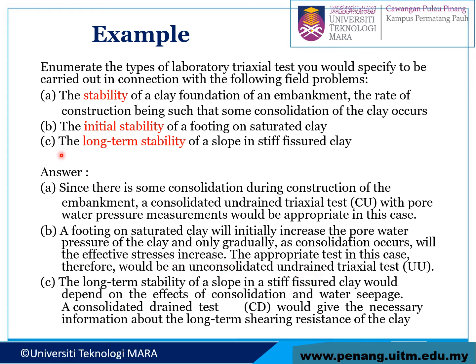For the last one, the long-term stability of a slope in stiff fissured clay. Since this one is long-term stability, of course this is for the consolidated drained test. But what is the explanation? The long-term stability of a slope in stiff fissured clay would depend on the effect of consolidation and water seepage. So CD is suitable and will give the necessary information about the long-term shearing resistance of the clay.